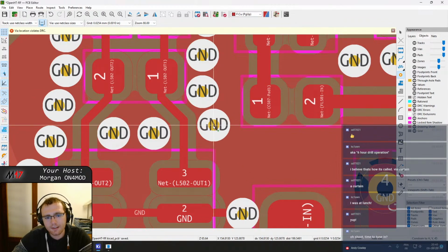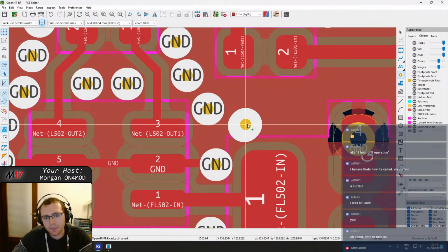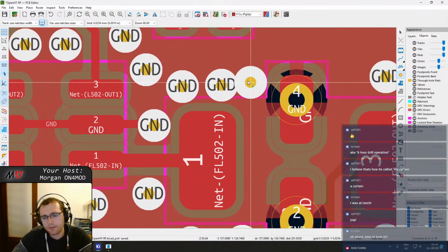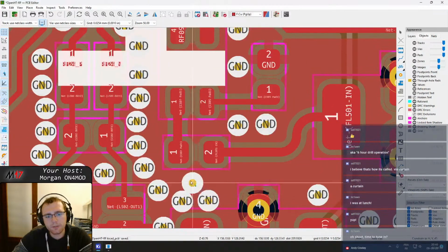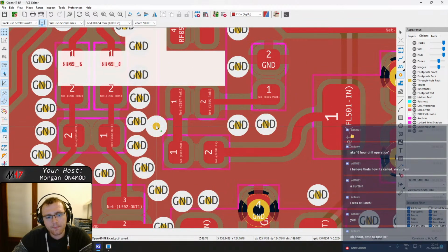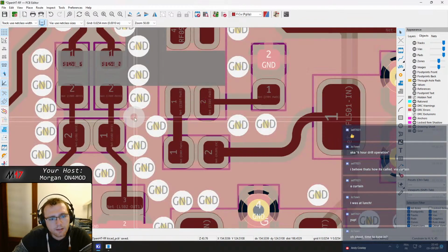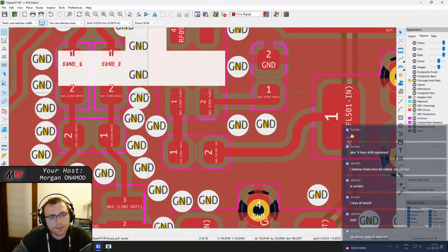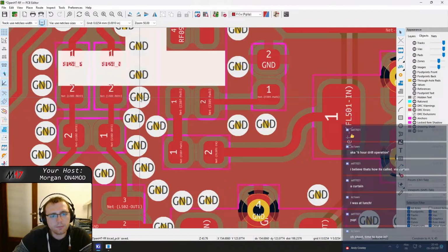It's not yet micro vias. It's more expensive. But then the micro vias, they are done via laser. So the thing is that when you do a large batch of boards, if you have like the starting price for the micro vias with the laser, it's more expensive because it's more expensive machinery.